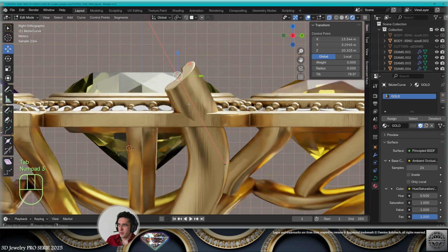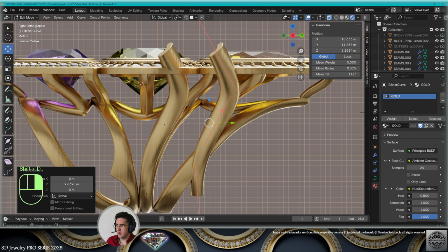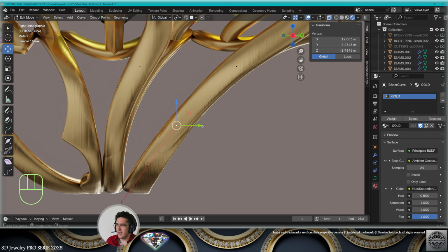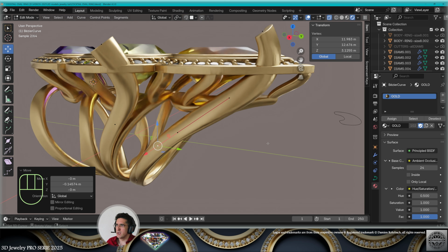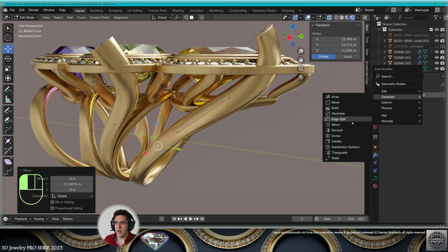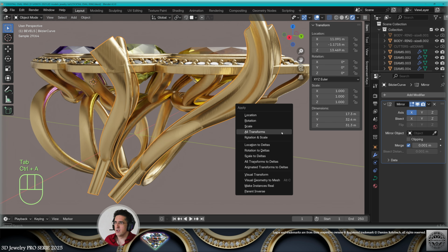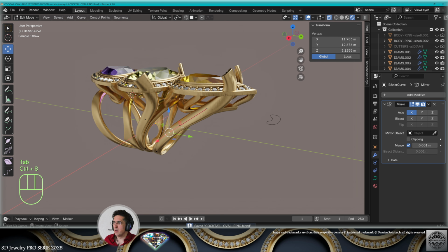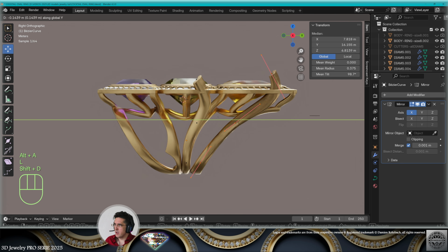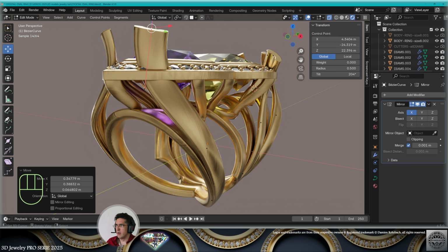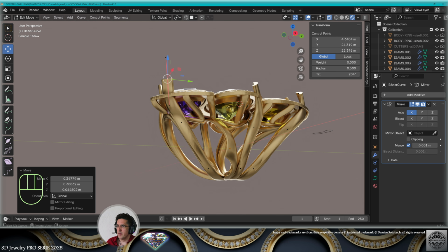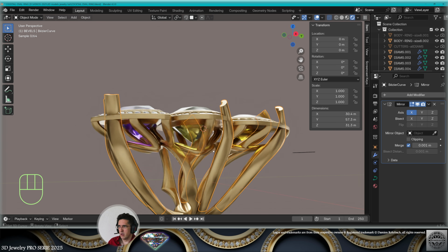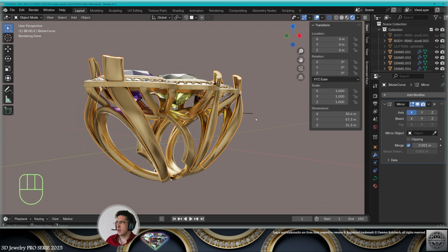And I'm going to copy on the y-axis. Here I can follow the lower structure. It's not necessary to do it like this, but in this occasion it's working wonders. I'm going to add the mirror modifier on the x-axis. So let's go out of edit mode and apply all transforms. Let's go back to edit mode. Now let's copy this again on the y-axis. Let's create this next element. So this is a beginning for this outer shell, but I want to add a couple more connections.